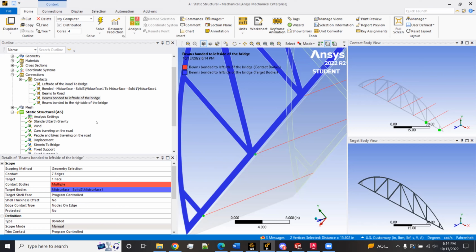Yeah, go ahead and give that a try, and then see if that fixes the pivot. I think what's happening is that it's trying to make a contact between the bridge and the beams, but these beams are so far apart from these that it doesn't know what to do. But if you put the vertices here, then it should be able to make the contact. Okay. Thank you. Yeah, and Charles makes a good point too. When you're choosing the vertices, just be careful. Go slowly and make sure you're clicking the ends of the beams. Okay. Thank you. Yep, I'll go ahead and fix that.